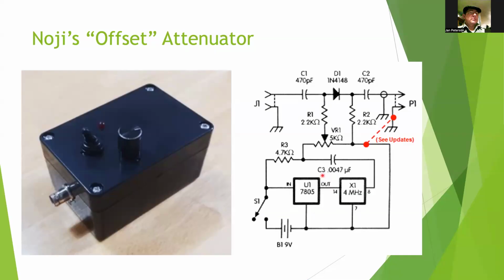So this is a capacitor. It's capacitor number 3. This is 0.0047 microfarads. This character right here is called a mu, and it means micro. It means 1/1,000,000th. So a millionth of a farad of capacitance is what this one is. There's one of these, and then there's 2 up here. These are 470 picofarads. So interestingly enough, 470 picofarads is the same as 0.0047 microfarads, isn't it?